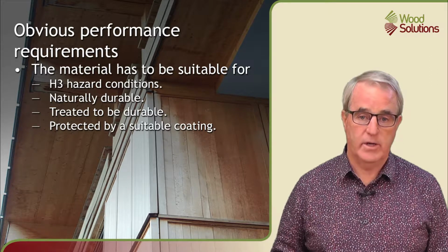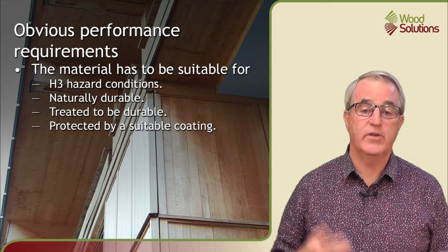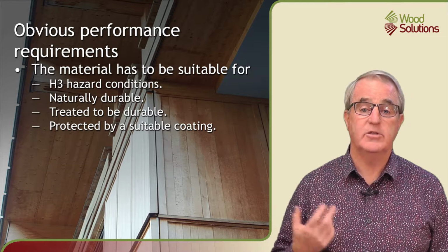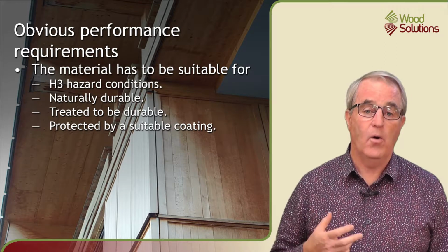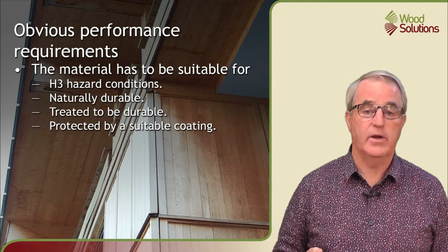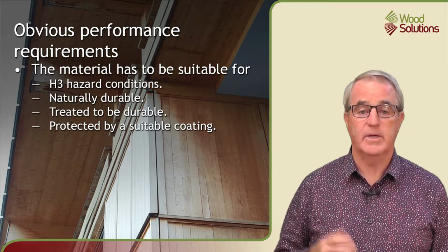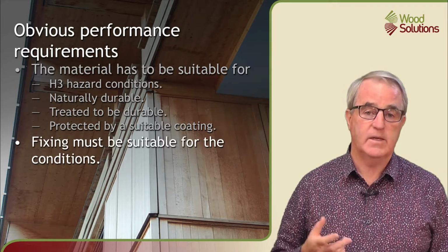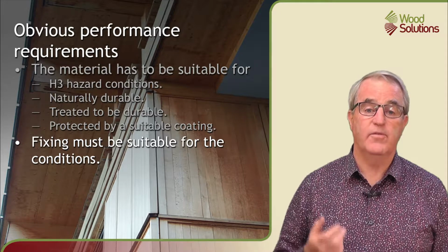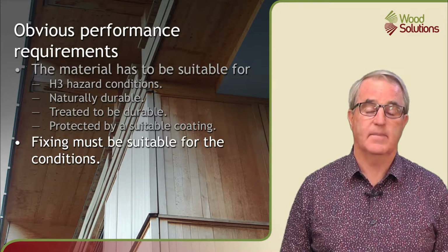If the timber is not naturally durable, it has to be treated sufficiently to be durable, that is, treated to H3. Or it has to be protected by a suitable coating, such as a quality paint or other protective system. The fixings also have to be sufficiently durable for the expected service conditions.